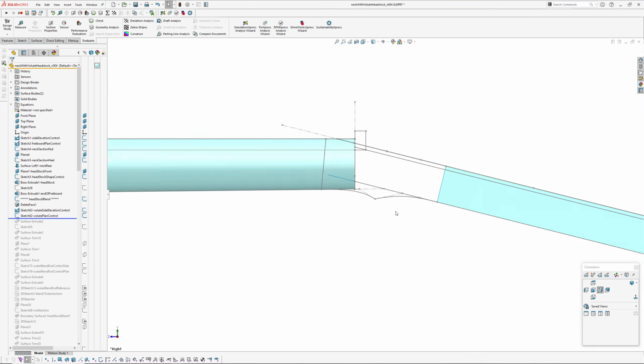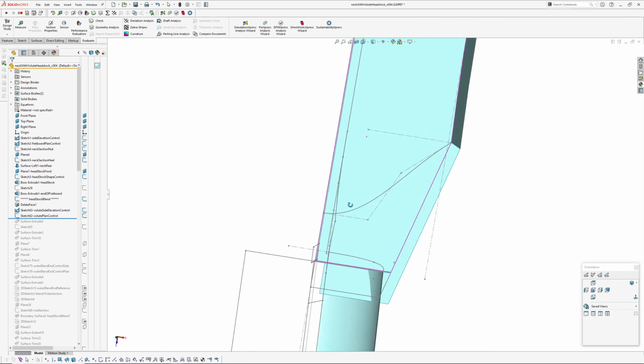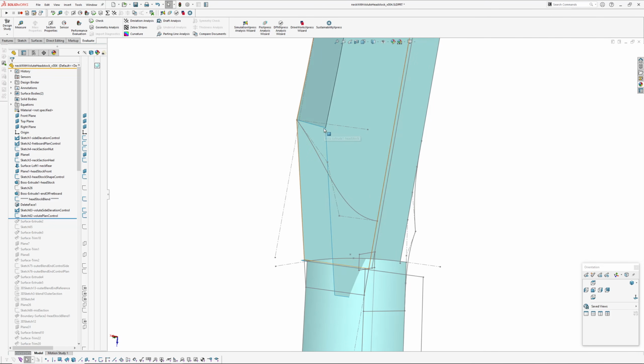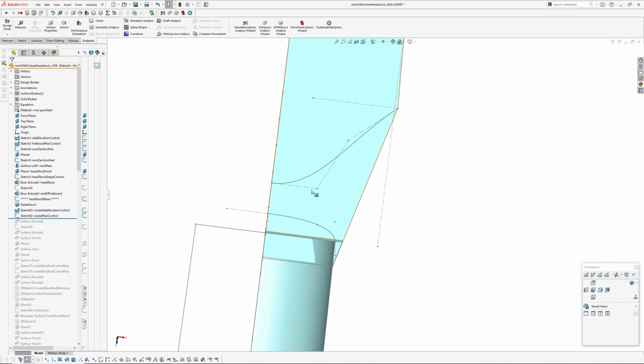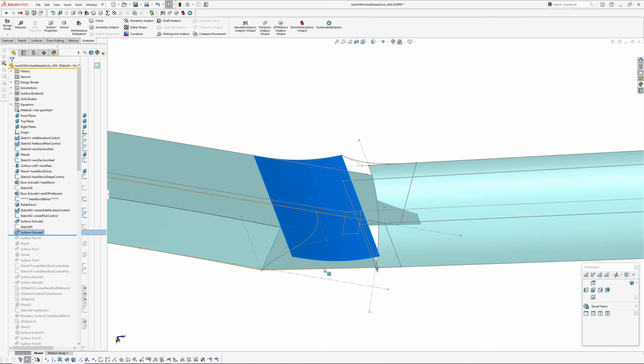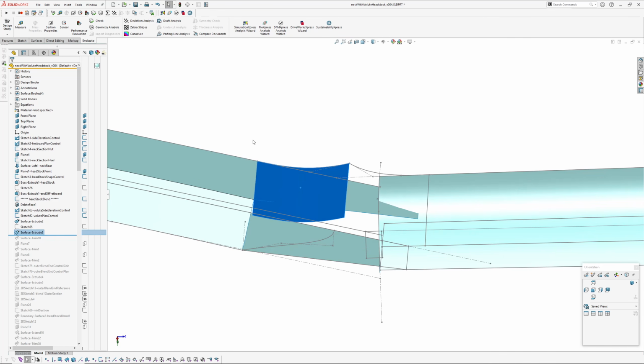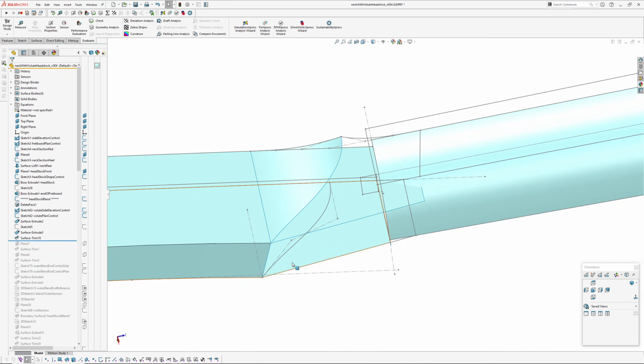Okay, next after that I've got the volute plane control. So basically in 3D space, the back edge of the volute. That's just simply a sketch there with, again, dimensions that you can change, these angles, and the length of the spline control polygon segments. Then I've extruded that section of the volute because this is the actual surface that's going to be running off the back of the headstock, and then that's trimmed back with the volute plane control.